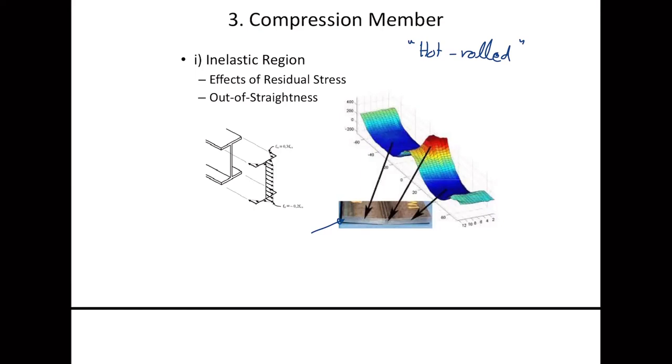But when the cooling process keeps moving inside, when it wants to cool down here at the junction, because it is connected to the flange on the opposite side and to the web, it becomes difficult for it to cool. Therefore this will create stress right there in the member, because the whole section cannot cool down at the same time. You can see from this picture that it curves up a little bit on both ends. That is what we call the residual stress. The stress is already there even before we have the load on the member.